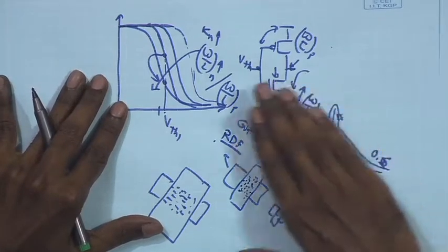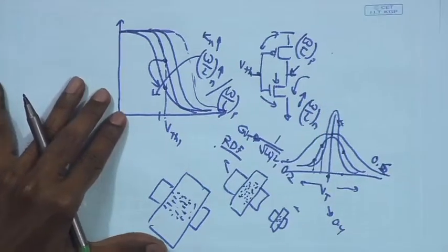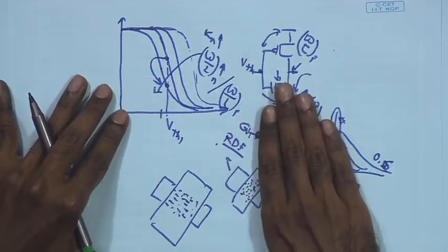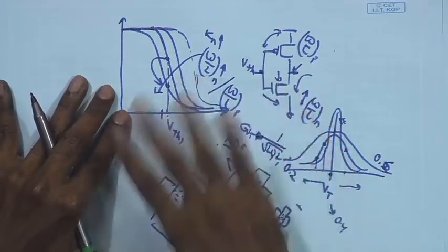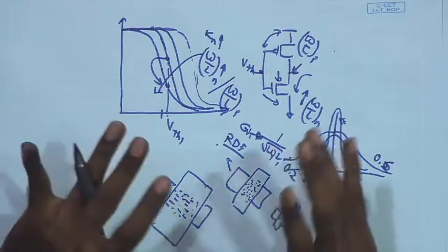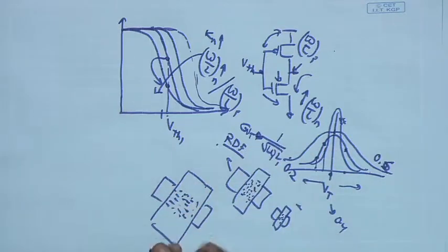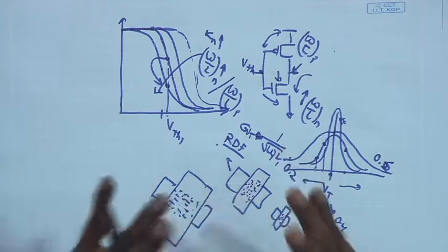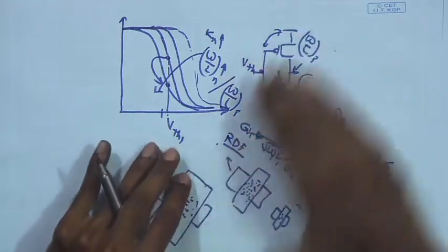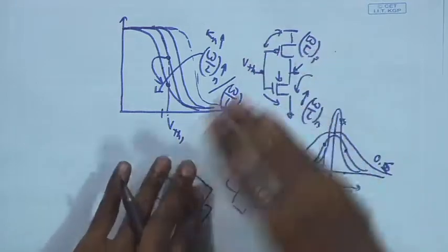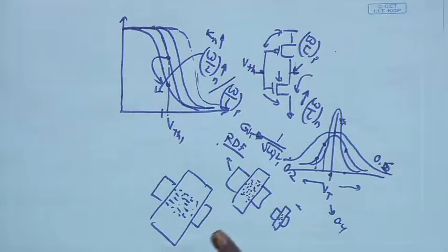Welcome back. Let us resume our discussion on the variation in mismatch and related issues. We just now discussed the implications of threshold voltage variations on the inverter transfer characteristics, and we saw how it is going to impact the interfacing between the digital inverter and the preceding analog stage. We tried to justify the use of the second stage in meeting the full swing requirement and having better robustness, and also making sure that the static power dissipation in the interfacing inverter is limited.